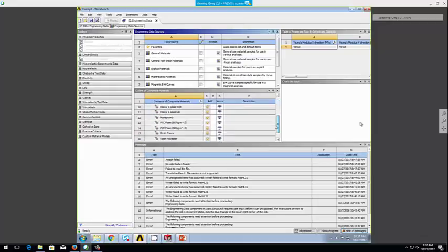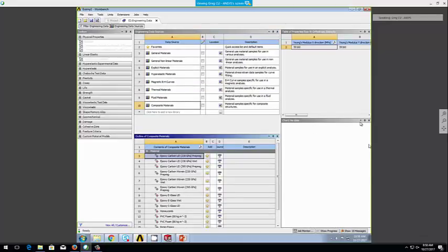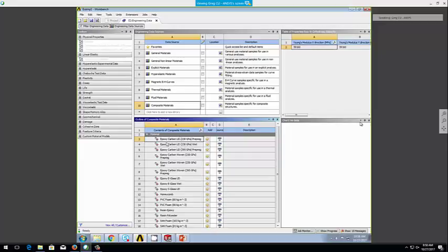One thing I don't like about this mesh, and this comes from experience, maybe it's too coarse, right? So I can actually come back here to sizing of the mesh and change to a fine mesh, okay? I'm going to have to remesh this, update this mesh. So now it's going to update, and you see here I've got some additional elements. The element size has gone down. Now what I've got here is the mesh.